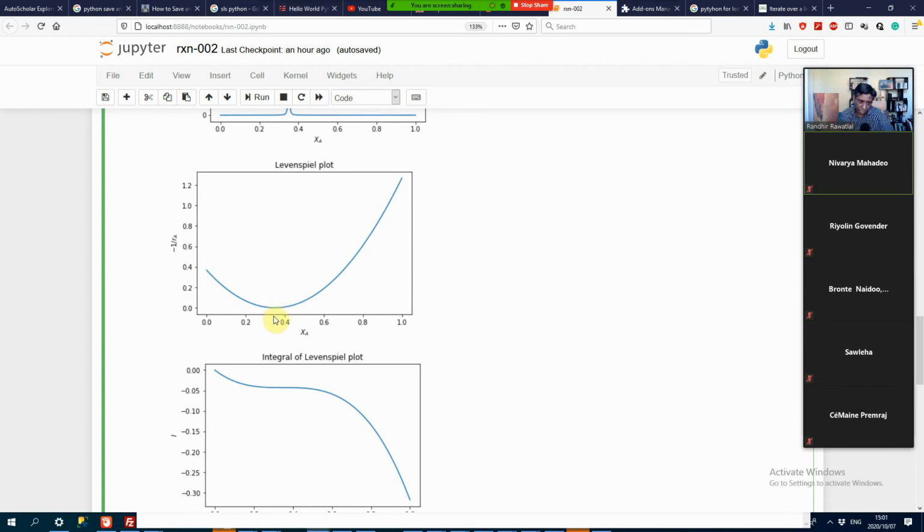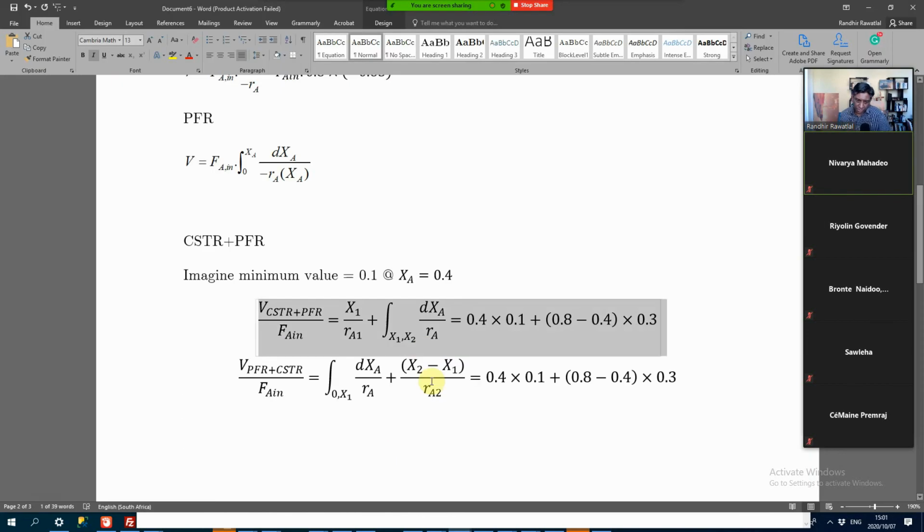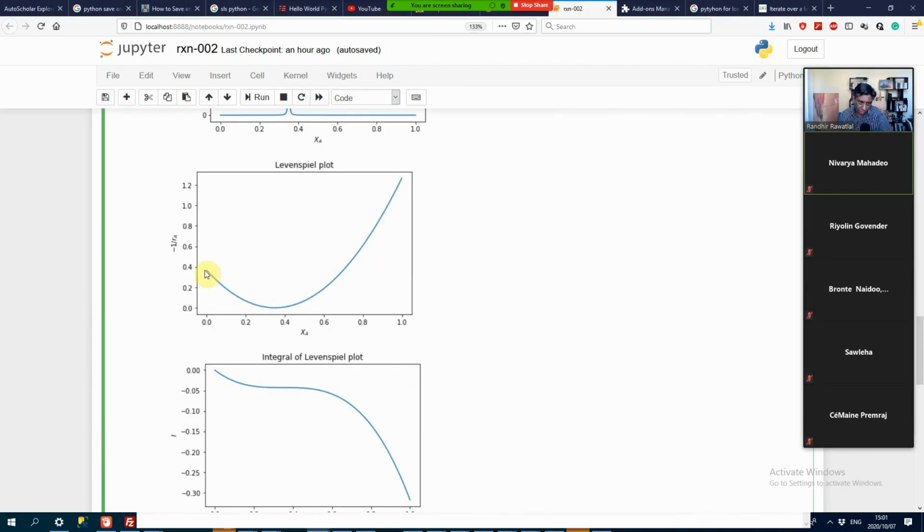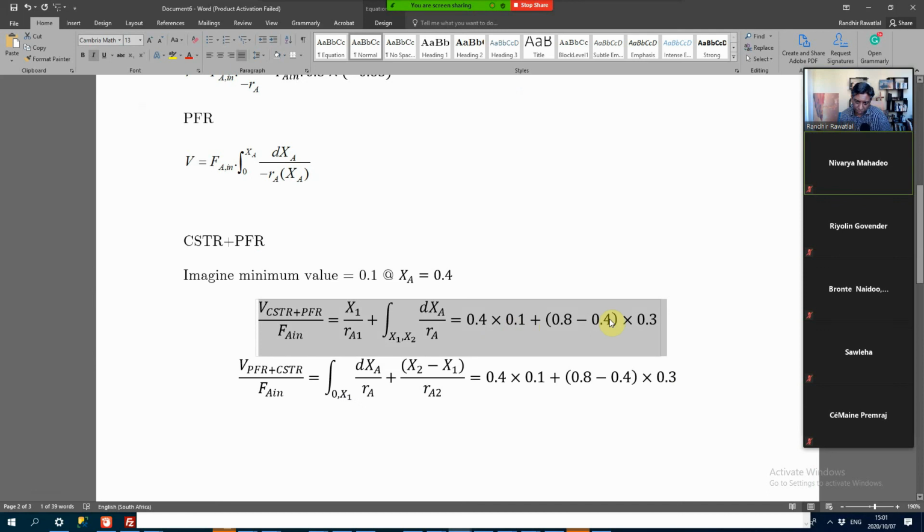So your content of your CSTR is the concentration at the exit point, so you use the exit conditions here. The reaction rate that we used here was 1 over RA is 0.1. We didn't use 1 over RA as being that inlet value. So this is the part to be careful of. I know it looks all very easy to approximate, but this is where we check. We have to get these numbers right. Okay, so you see that's going to be different now in this case.